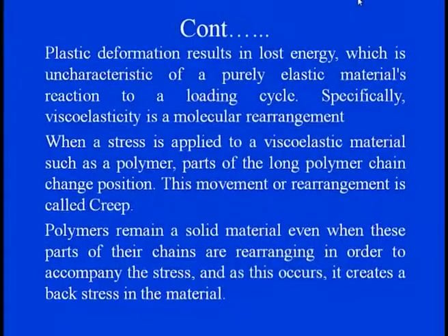So the polymer remains a solid material even when parts of its chains are rearranging to accommodate the stresses, and as this occurs continuously, it creates a back stress in the material. Sometimes we say that this is a pre-stressed feature, because all these stresses are closely coupled with the material, as this happens in every cycle in polymers.